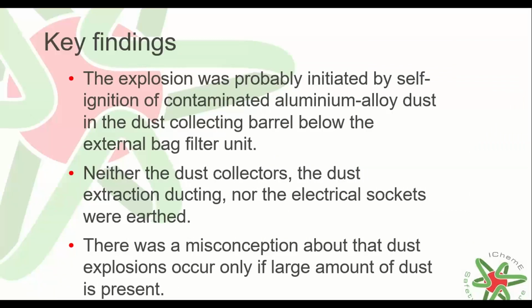Let's see what we can learn from this particular case. The investigation concluded that the explosion was most probably, because they couldn't identify the exact cause, initiated by self-ignition of contaminated aluminium alloy dust in the dust collecting barrel below the external back filter unit, in which the initial primary explosion took place.